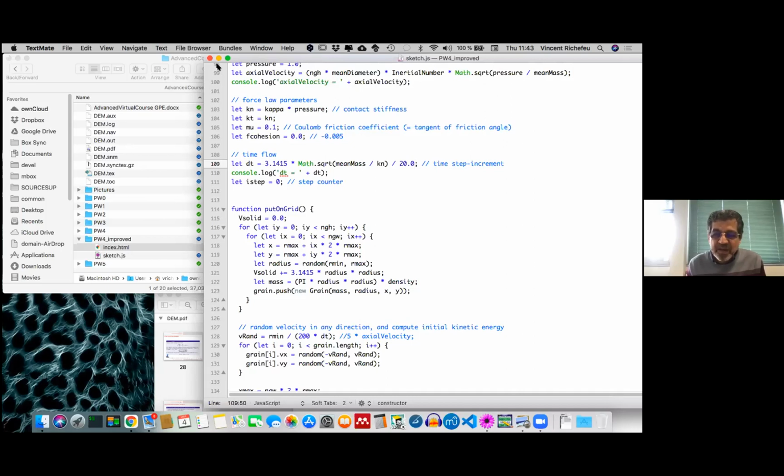Okay, a question by Yiqiu Zhao. You mentioned that in simulation, I, inertial number equal to 10 power minus 3 is considered quasi-static, but this may not be the case in experiments. Why this value may be not considered quasi-static in experiments? No, in experiments, they are not, because we make experiments by changing the inertial number. And we find that the transition may be for lower values. I don't know, actually, maybe 10 at the power minus 5. Sometimes we make experiments with I equals 10 at the power minus 9.